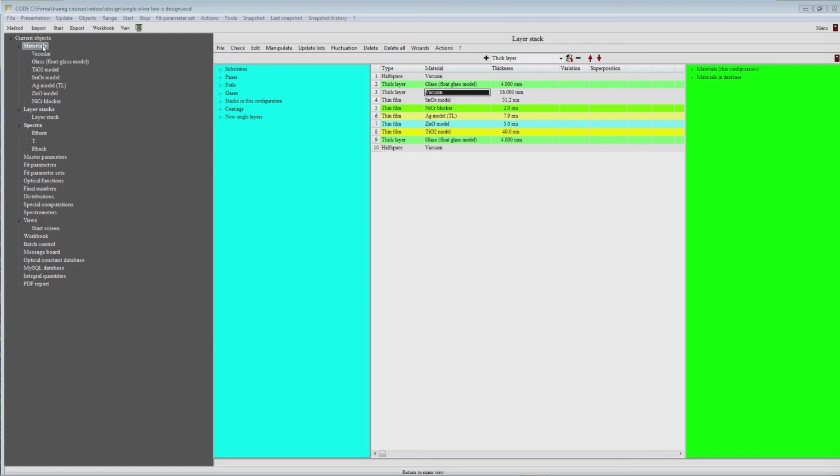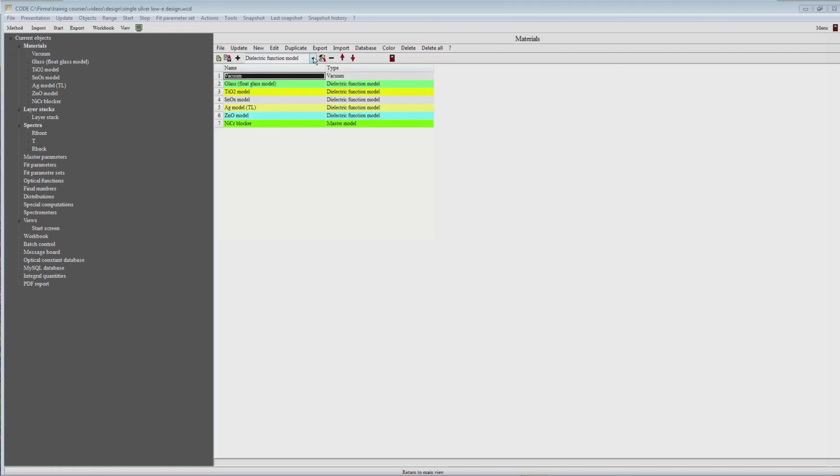We go to the list of materials. We select as new object type a material type called gas, which is at the bottom here. So we generate a gas. We can call this already now argon 90, because we are going to define 90% argon and 10% air, which is a frequently used mixture of gas if it comes to technical applications.